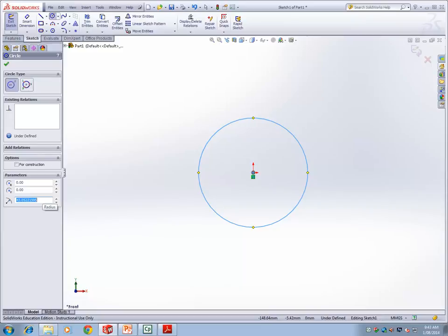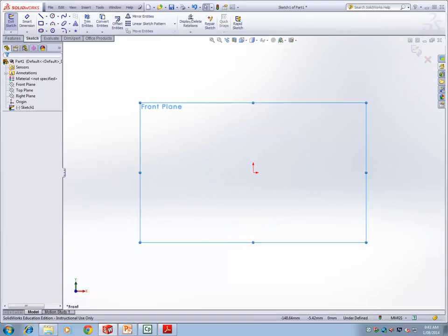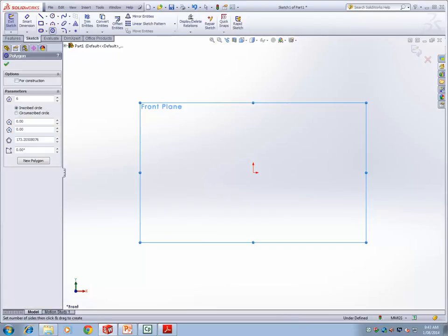But things like when you're drawing the polygons, there is a difference between an inscribed circle and a circumscribed circle. When you're inserting, you're basically giving, for this particular entity, the number of sides, and that would be enough, and just choose whether it's a circumscribed or inscribed circle. So I'll quickly show you snapping the origin and drawing the hexagon.